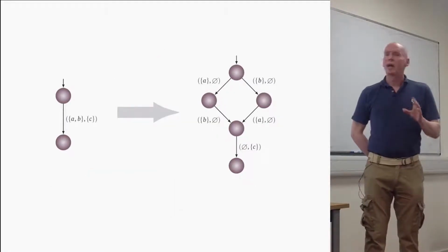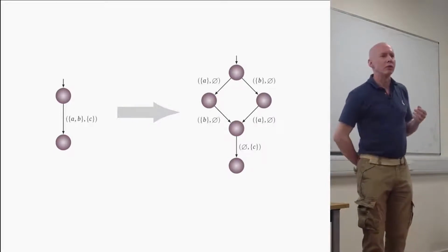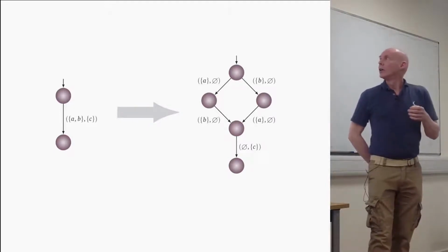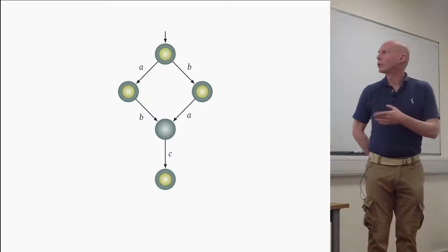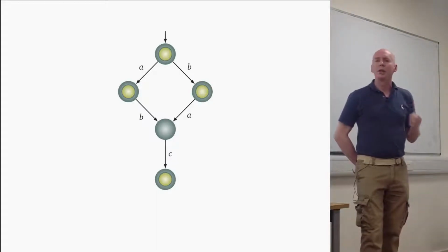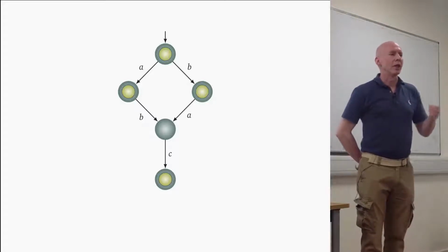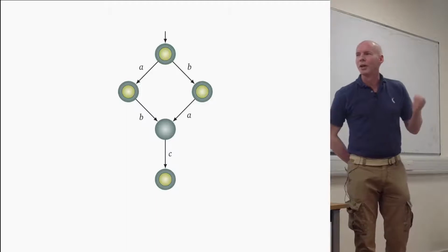This is a more compact representation, but it also puts us on the way to learning something useful about the circuit. If we take a transducer model and we expand it if necessary to have at most one signal labeling each edge, we have something isomorphic to a state machine, and if we designate the accepting states as those whose outgoing edges are labeled only by input signals, the machine recognizes the quiescent traces of the circuit. Those are the traces leading to a point where the circuit will emit no further output unless it gets more input from the environment.